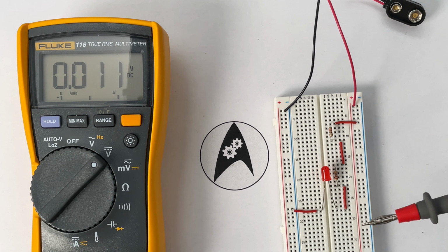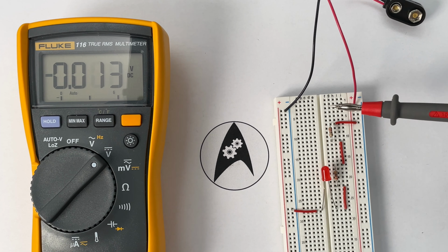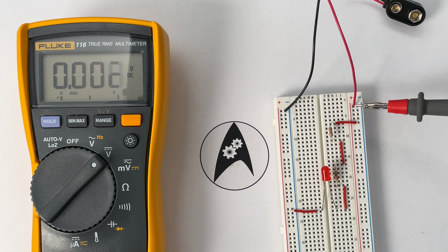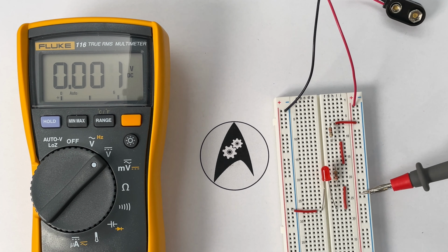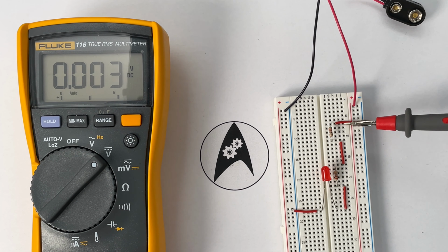What you can see here is a so-called breadboard, and this breadboard is designed as follows. These outer connectors are the so-called power rails, and they are connected from top to bottom. So this means that the plus cable leading to the battery in a few seconds is connected all the way down to the bottom with all the holes in the same column here. And it's also connected with this jumper cable here, with this connector which leads into the center part, about which I will talk in a few seconds.